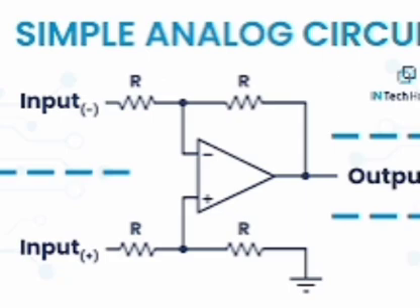Analysis of small signal amplifier. Introduction: in the analysis of small signal amplifier, the transistor is replaced with an equivalent circuit known as small signal model. Small signal models include the hybrid parameter model, pi model, and T model. These are all used in analysis of BJT amplifiers at medium or low frequency. For high frequency, the hybrid pi model and T model are used. Now, low frequency analysis of BJT amplifier: hybrid parameter model.